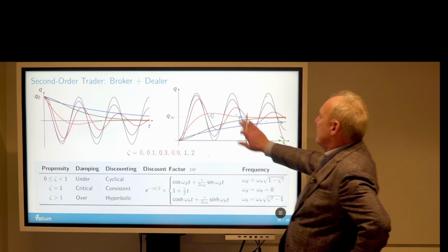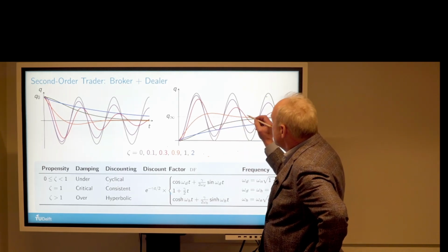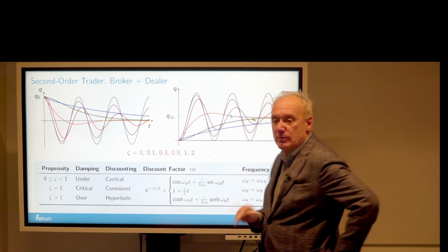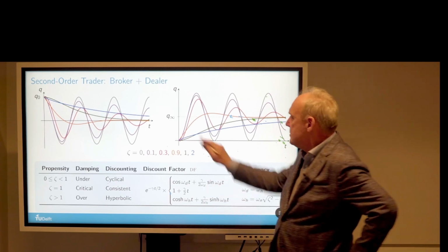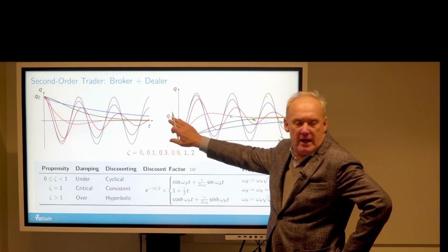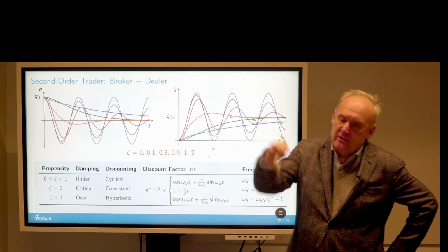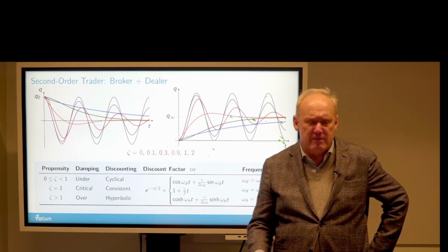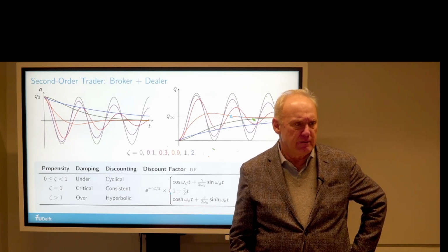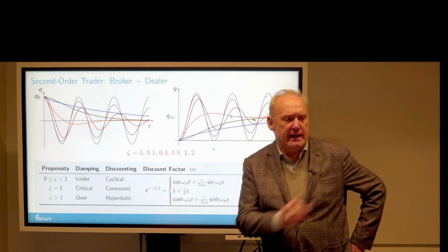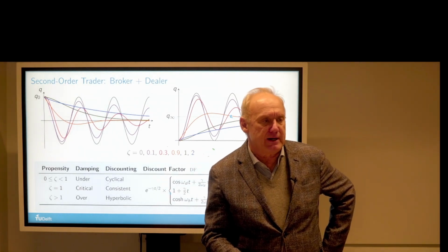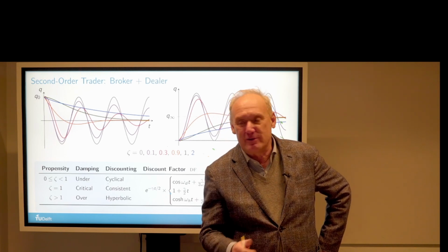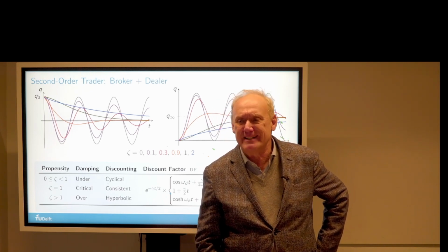So if you don't want to allow any overshoot, you're going to pay a price, because you see, this thing settles, if you have some kind of settling time where it's within so much percent of your desired stock level, right? And you want to get there as fast as you can. It's better to overshoot a little bit and then come back. That's just a much faster way to get there. Now, sometimes that's not desired with a door, but suppose you brake a car at a traffic light. You could go much faster if you were able to overshoot a little bit, and then you're going to cause an accident. So you don't want to do that.